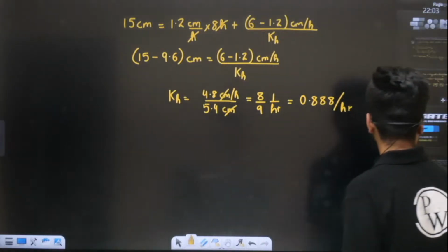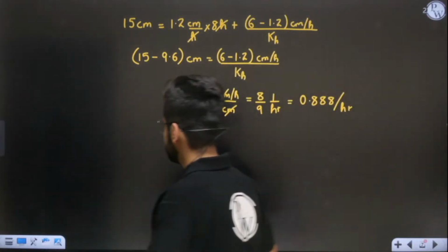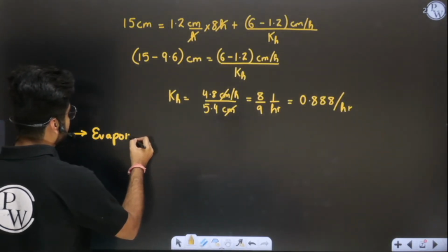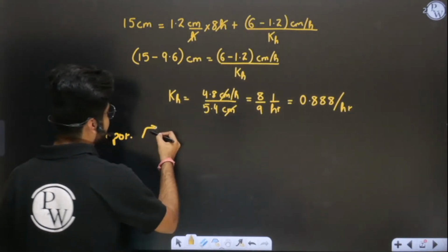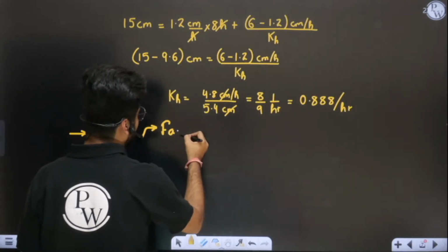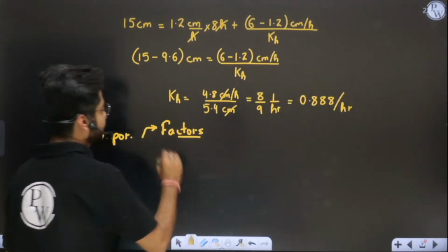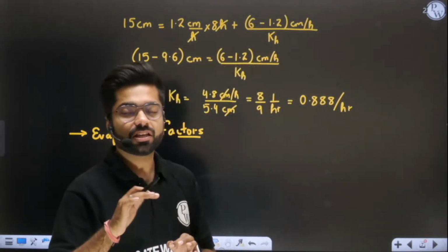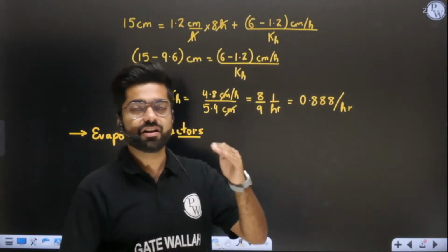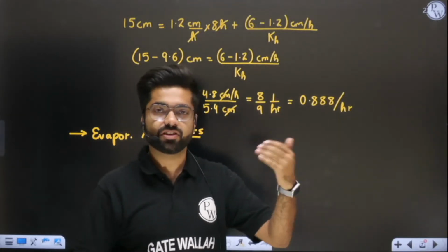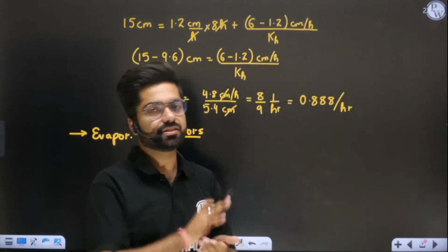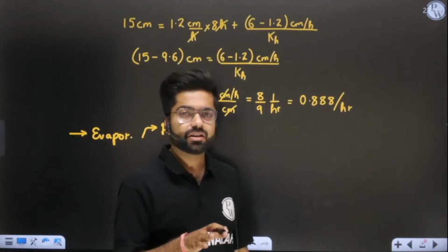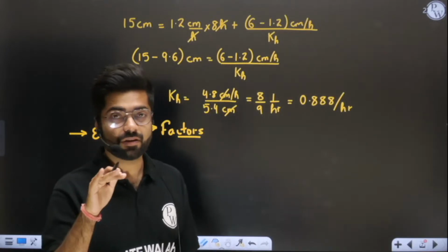In losses from precipitation, the very first topic which we discussed was evaporation. In evaporation, I told you the basic definition and the factors on which evaporation depends. When atmospheric pressure and vapor pressure increase, evaporation goes down. When wind velocity, temperature and surface area increase, evaporation increases. Only this much you have to remember. When water quality goes down, evaporation also decreases.